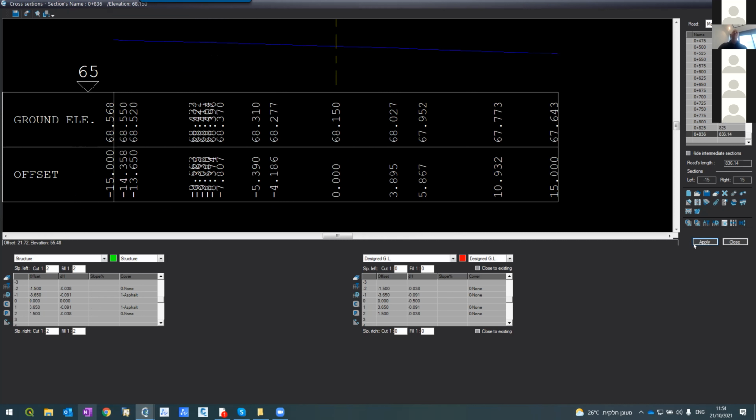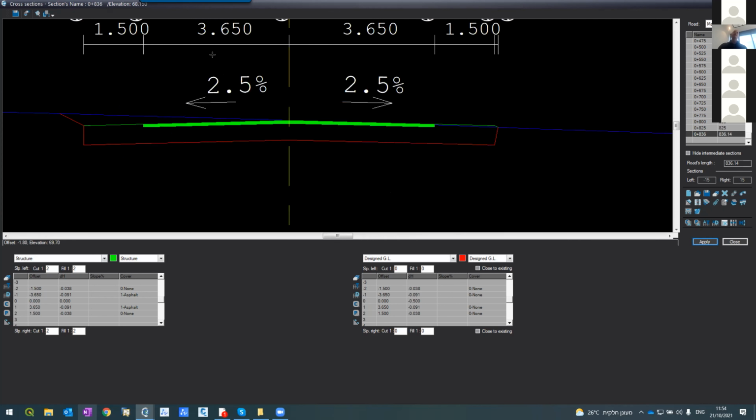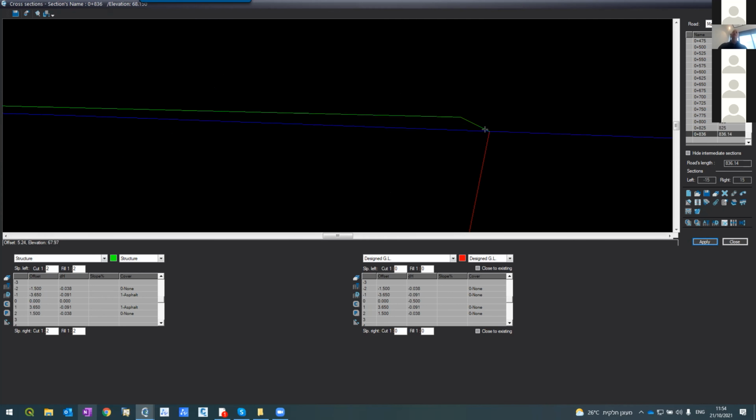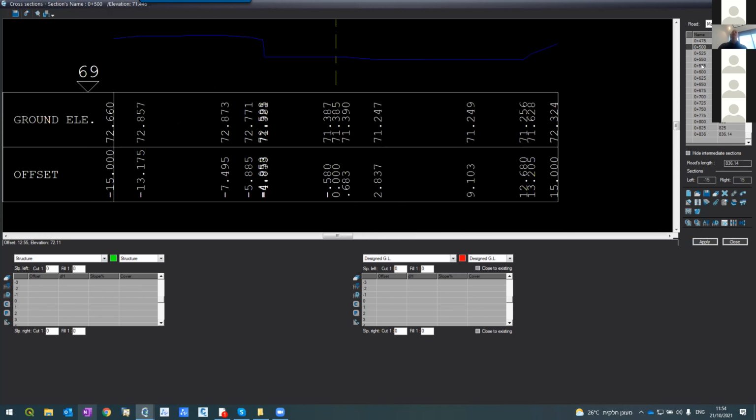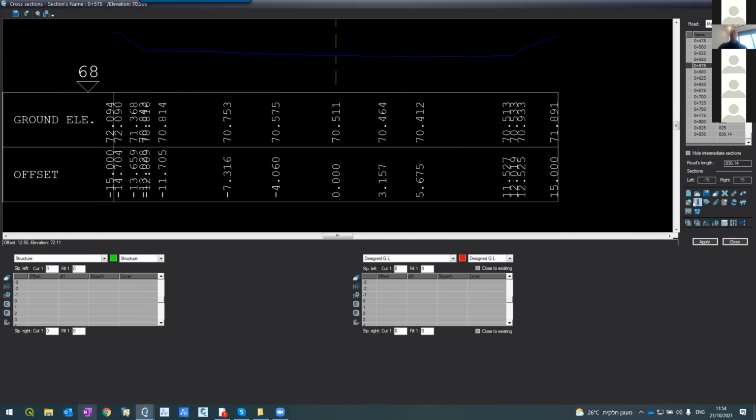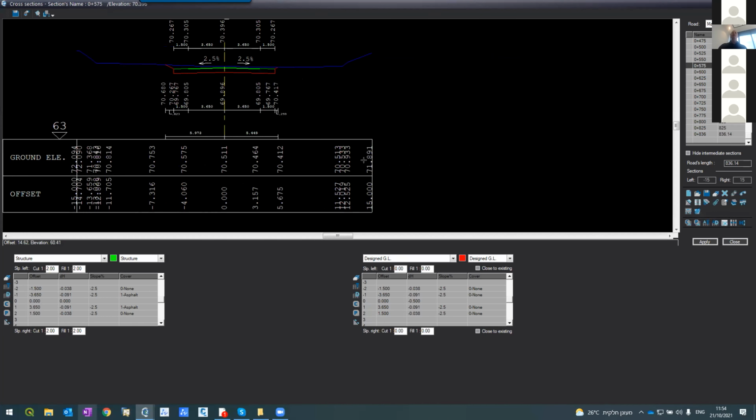All the data from the first section was copied to here. If I press apply, this is the last section. Here I'm a little bit in fill here. The rest are still empty. So what I want to do now is to interpolate between the first and the last for empty section. You see, interpolate empty section. I'm pressing the button, pressing all design, and that's it.